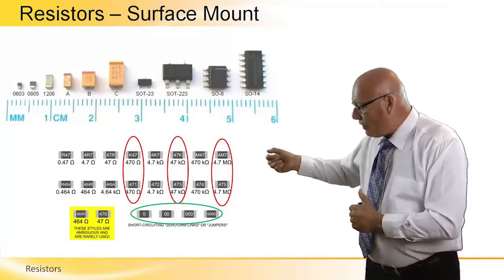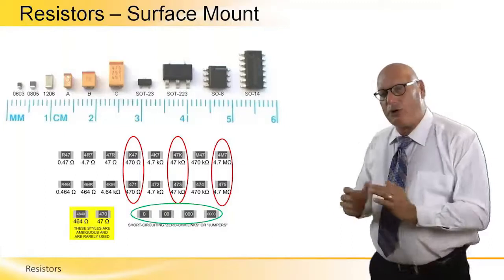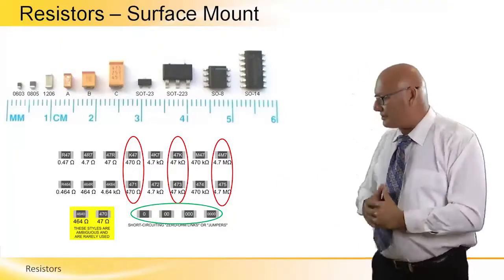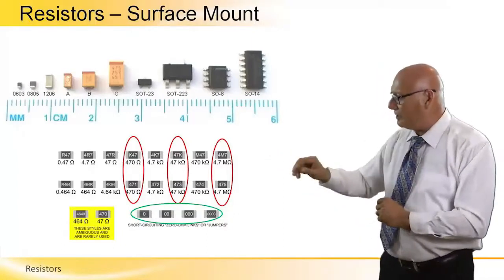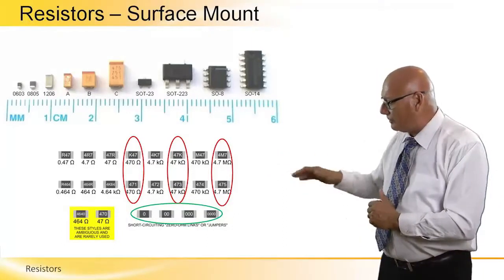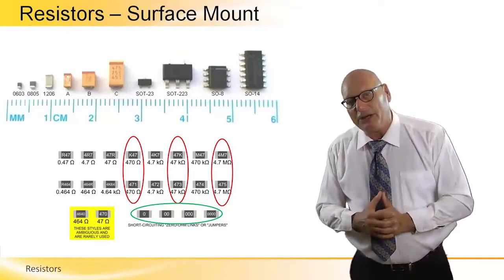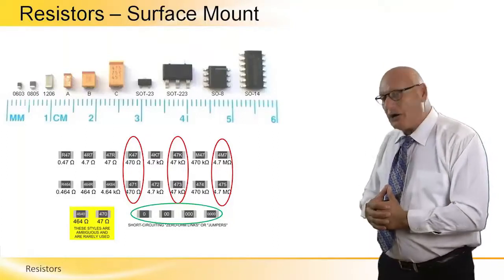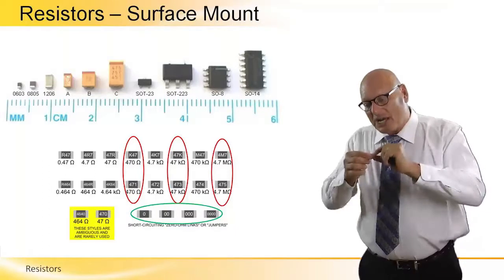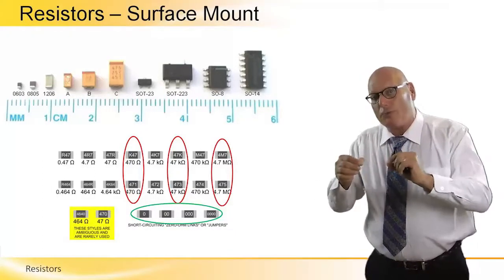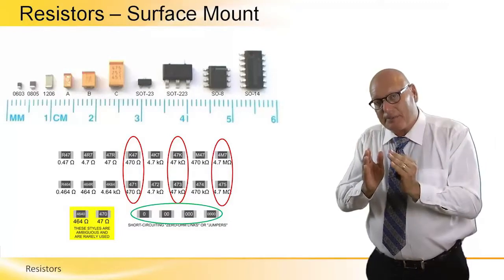It's written in one way, and there are two different codes in terms of how to read. It's written in both ways, and they're both okay, just different standards. And let's actually evaluate the two different standards, the upper line of resistors and the lower line of resistors. And the ones that are circled in green elliptical shape are jumpers. They are basically components with no resistance. They are a short, 0 ohm resistance. So there is a short between both of the end caps.